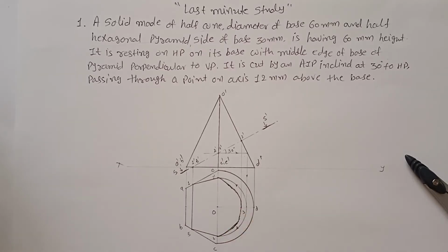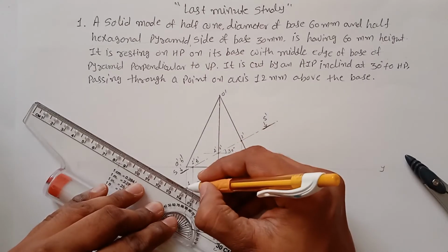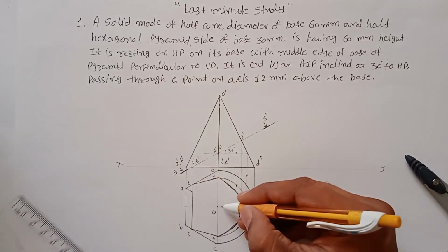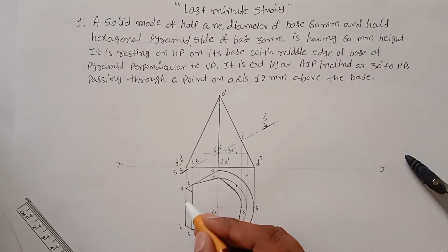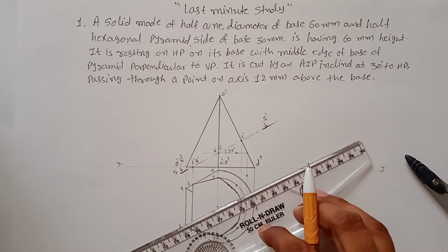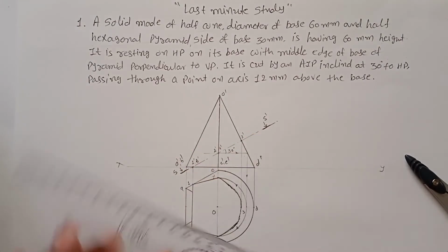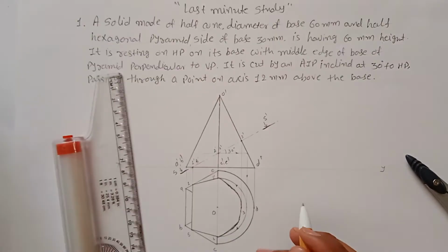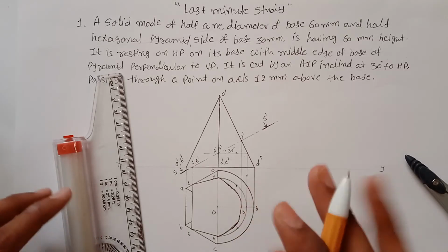Okay, now you have to draw those lines which are connected to the center line, which are not visible after cutting. Initially you draw it connecting with the O, but after cutting those edges will be cut, so you can only see this much portion, and again here also only this much portion. Same way for this and this. Actually you have to draw a thick line also, but this is a cone, there are no edges involved, but this is the thing.